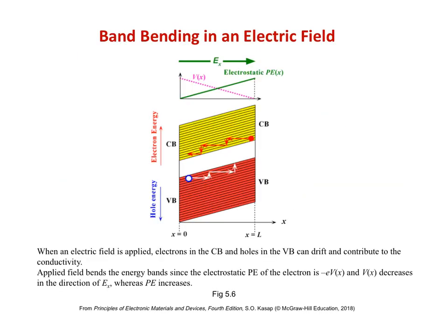When an electric field is applied to a material in the x direction, that means the electric potential changes linearly from one x position to another. The applied electric potential leads to a change in the electrostatic potential energy of electrons in the material. For such a problem, we typically draw our energy block diagram as a function of position using the horizontal axis for position.